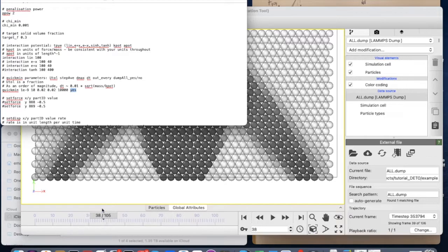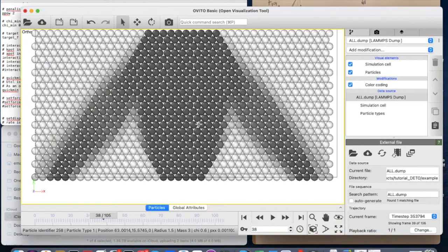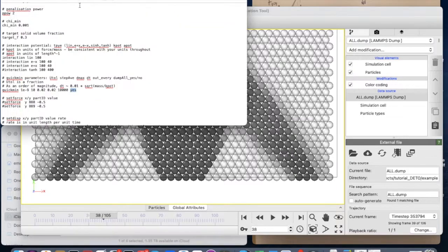But in general, when you just look at the results of an optimization, when you are confident that the system is equilibrating properly, then you don't need to produce this output file that can be very demanding and very large. So you can use a no here. I suggest you use no except when there is a good reason for you to look at the details of how the system is deforming under the imposed load or imposed force.